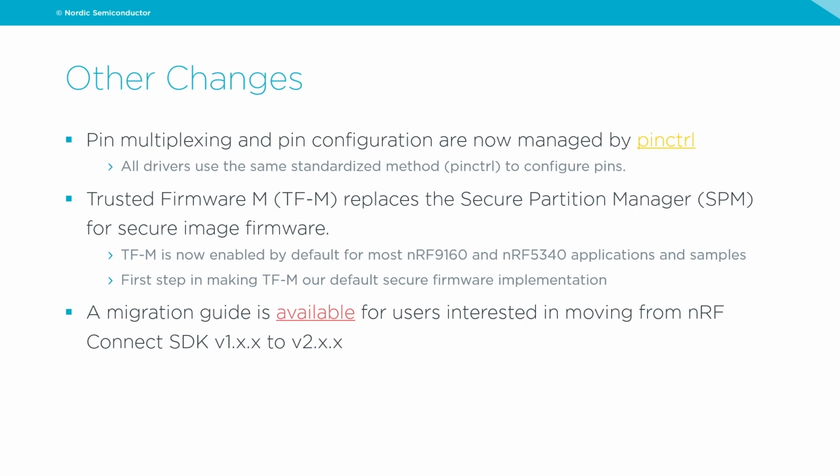And this also has the implication that the representation of hardware, which is through device tree, is now changed. So it uses something which is defined in the pin controller subsystem called state model. So you have different states, and then these states represent the pin configuration set to them. So if you have, for example, a UART node, a device tree node, it could have two states: when the device is active and when the device is asleep. So it's a standardized method to configure pins.